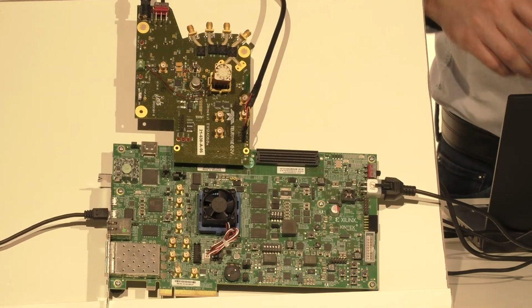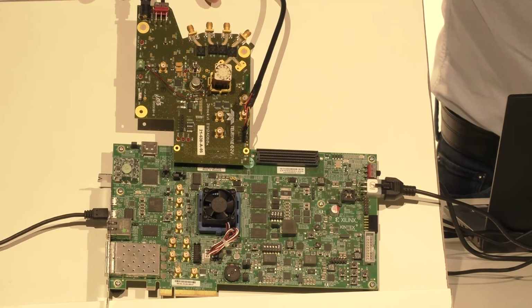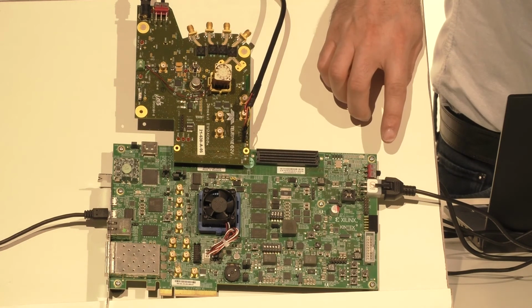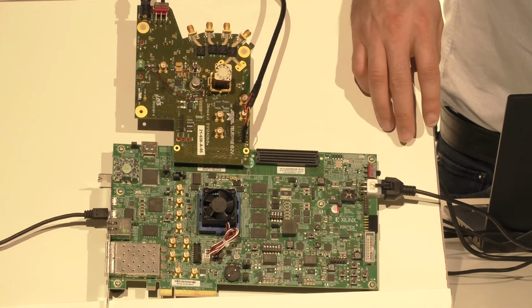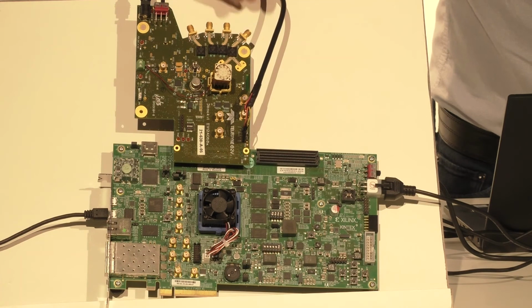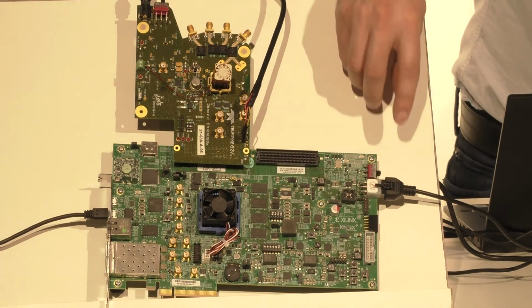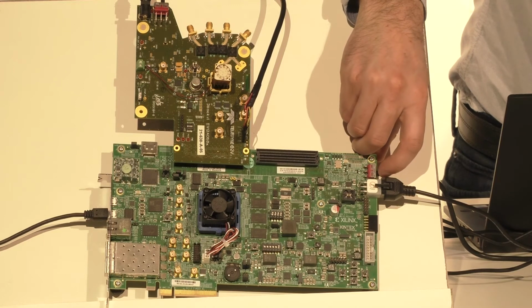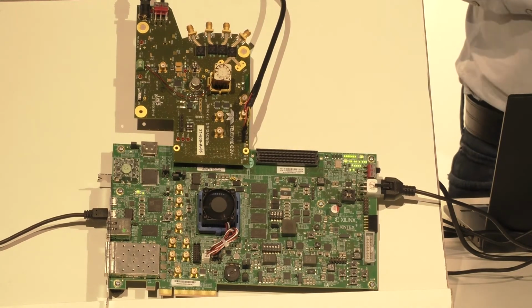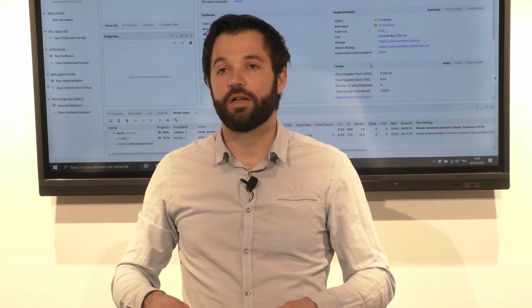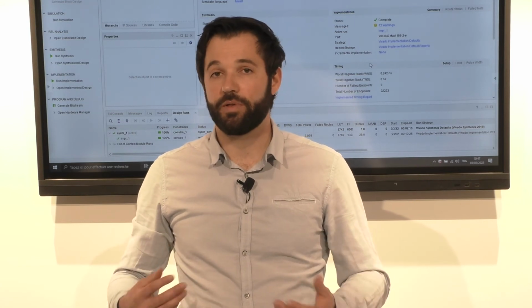Before powering on the FPGA board, check that all power supply switches are in the off position, then connect the power cables, UART cable, and JTAG cable. Now you can switch on the FPGA board. At this stage, you can program the FPGA.